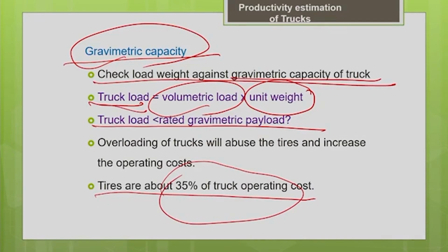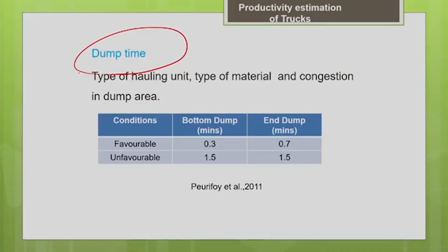Keep in mind that by adding side boards and overloading the trucks, though you are able to increase productivity for a shorter time, those benefits will be only short-lived. If you keep on overloading your truck, it will result in premature aging of the truck and huge loss for you. It will result in yearly replacement of your truck with a new truck, which means huge ownership cost. That is why you should not overload the truck.